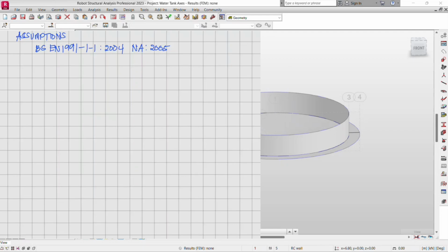For this presentation, we will not complicate it, so we will be omitting the crack width check. That's coming from your flexural crack width, basically the quasi-permanent loadings, and so on, and of course following the provisions of the Eurocode. We will do a separate video for that. For this, we will be assuming a maximum settlement of around 50 mm. That's for water retaining structures.